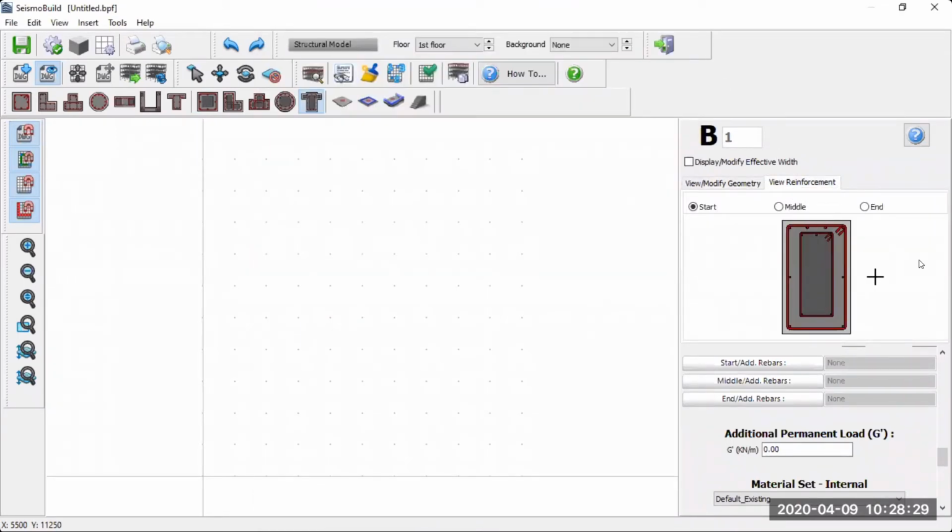All right. So in the next tab here, we can also insert slabs, and this function helps you insert your slab elements. And last but not least is inserting the staircase. Based on our experience with some old structures, if you include the contribution of the staircase, it also indirectly helps in terms of the seismic performance of the building. All right.